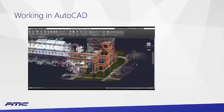Like I said, we used to actually show people how to use point clouds in AutoCAD and Revit. I tend to not even do that anymore. If you're totally new to this and you have no idea, there's plenty of really good videos from Autodesk that show you how to do this, but it's honestly as easy as attaching an XREF and the point cloud simply shows up. And you just draw right on top of it. And you can snap to the points using 3D snaps.